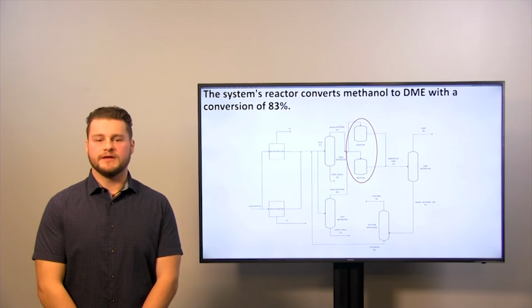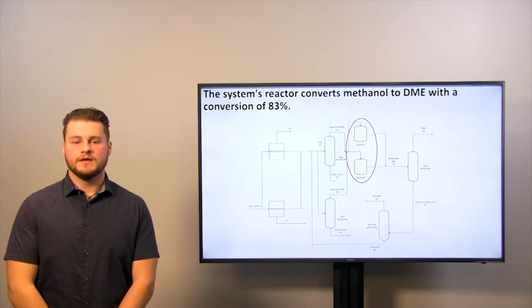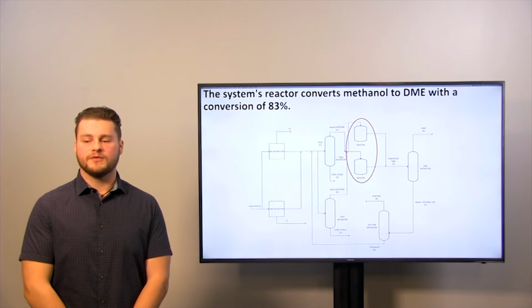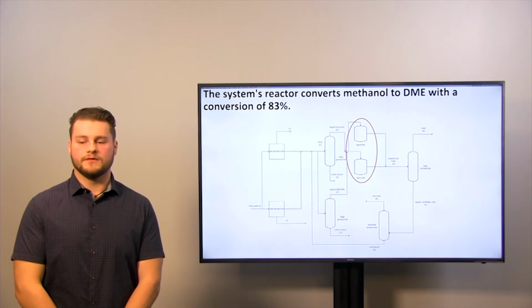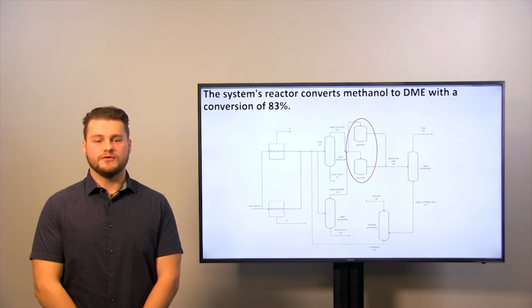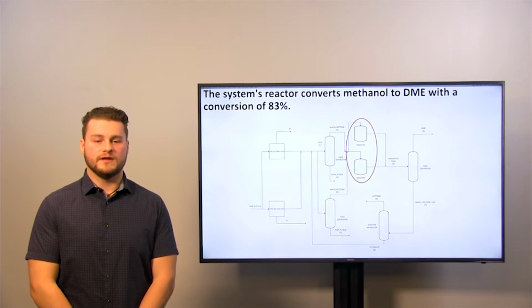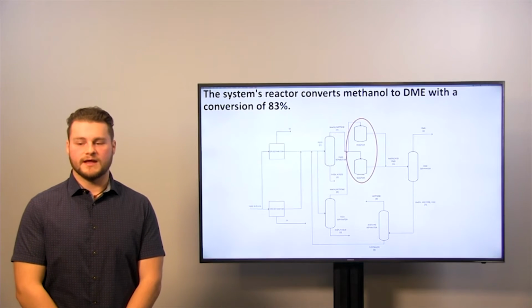After the feed is split in the two distillation columns prior, this mixture is then sent to reaction. This mixture contains 89.3% methanol and the remainder acetone. The feed enters a system of two parallel reactors. One reactor is run at a time, as the other is saved for times of maintenance and to regenerate catalyst.